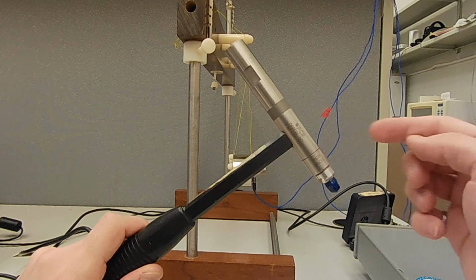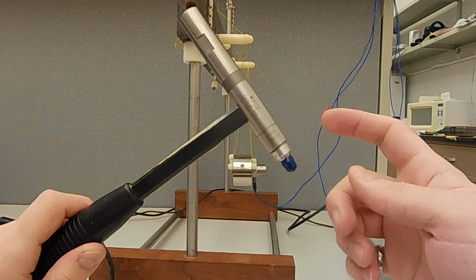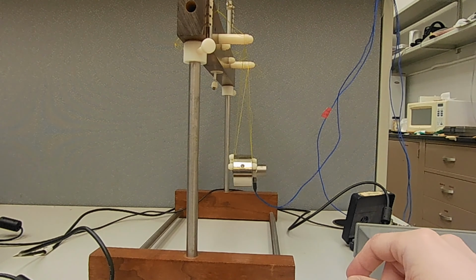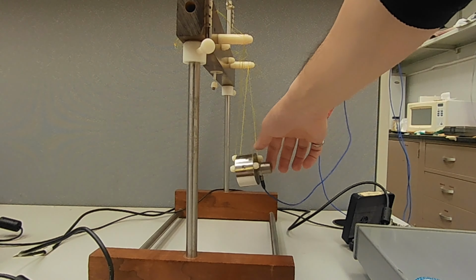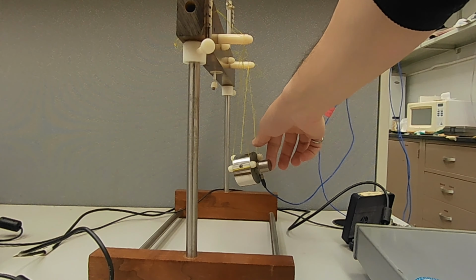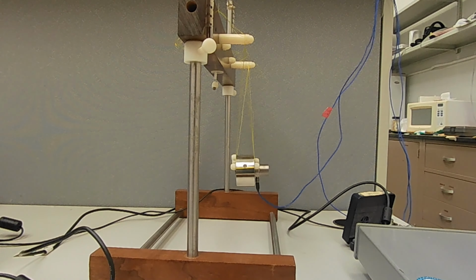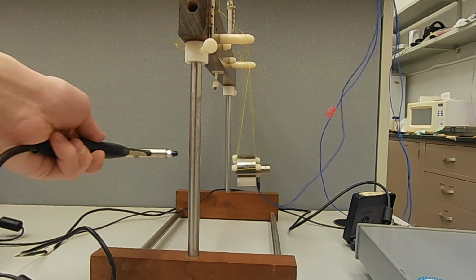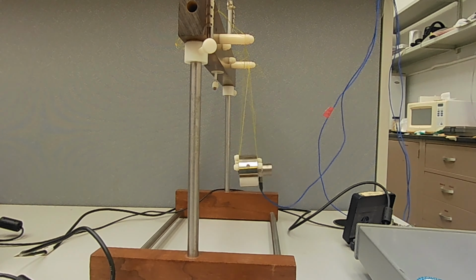All right, so this is my test hammer. It's got the load cell in front of it, so upon impact it's able to measure forces. And I want to now identify what the sensitivity of this test hammer is. To do this, I have a pendulum apparatus in front of me comprised of the piezoelectric accelerometer we identified the sensitivity for earlier, and we have a known mass. So what I can now do is bring into impact my test hammer with the pendulum, and from the measurement results and some of the parameters we already know, we're able to identify what the sensitivity of the test hammer is.